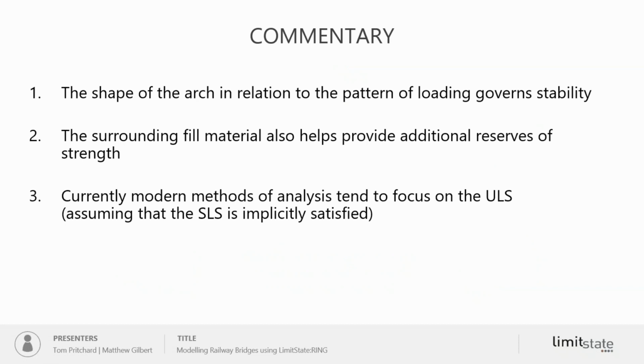What we can say if we step back is that this is the shape of the arch in relation to the pattern of loading which governs stability. We also, in addition to the arch barrel, have surrounding fill material that also helps provide additional reserves of strength. What it basically does is provide pre-stress from the self-weight. It provides distribution for whatever live load you apply to the fill, and also it provides passive restraint as the arch barrel wants to sway into the fill material.